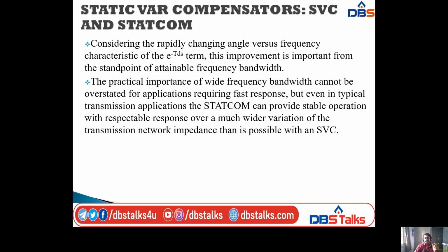The practical importance of wide frequency bandwidth cannot be overstated for applications requiring faster responses. But even in typical transmission applications, the STATCOM can provide stable operation with respectable response over a much wider variation of the transmission network impedance than is possible with the SVC. Overall, the STATCOM is better than the SVC.